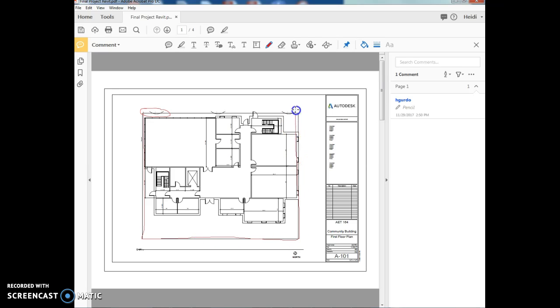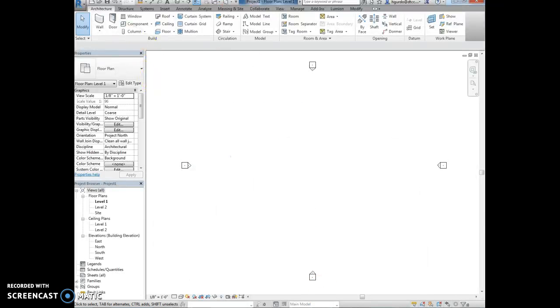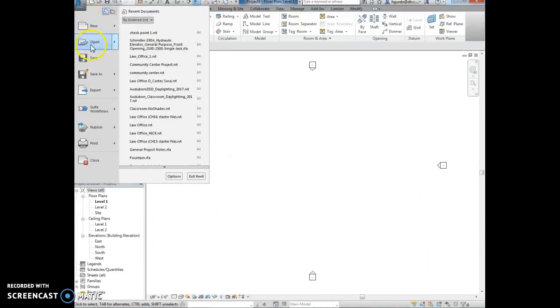Like this, you want to hide that. You want to hide those trees too that are shown. So if you right click on those elements in Revit, you'll see a button that says hide elements in view. Let me open up an example so that you can see.